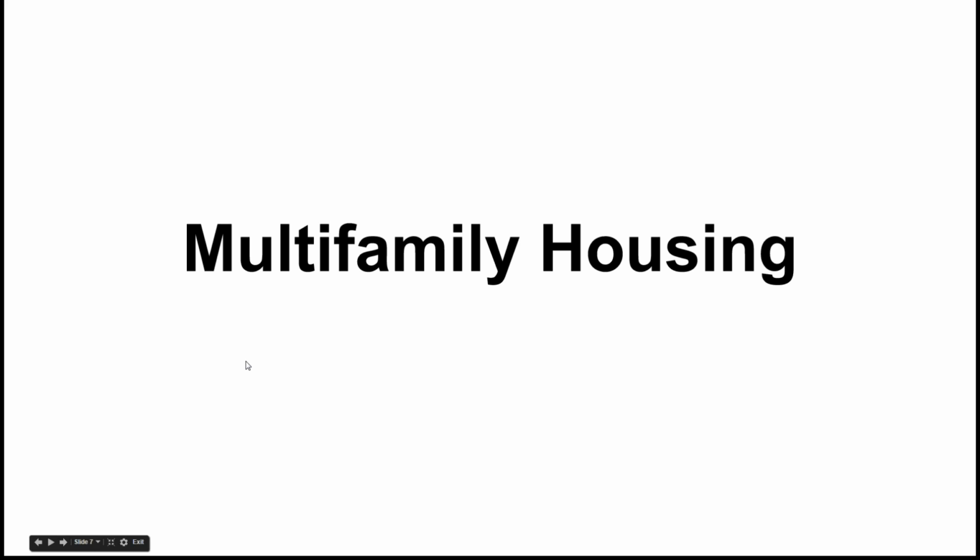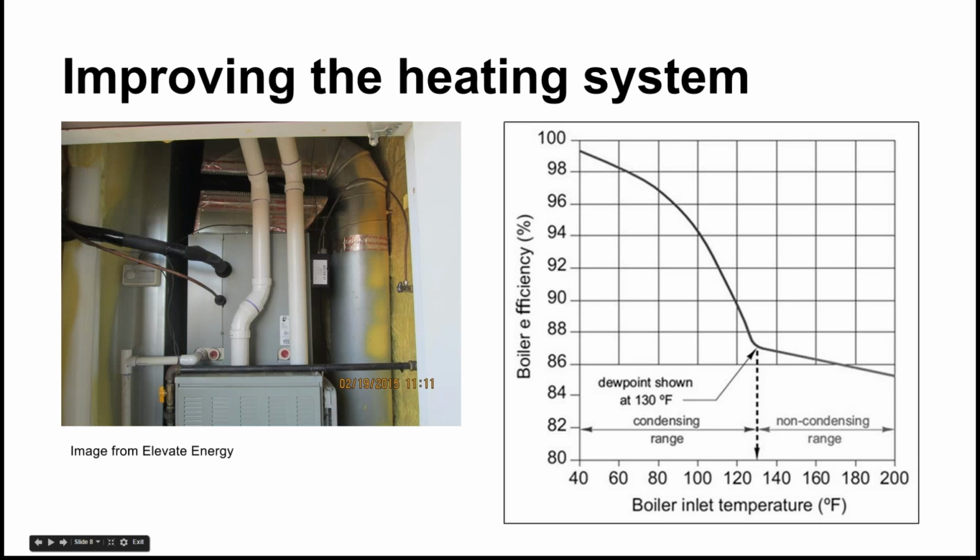So looking for every tiny place that you could air seal is maybe not the best choice here, but focusing on adding roof cavity insulation is a really good choice. It's pretty minimally disruptive to tenants. You can get it done within a day or two, depending on the size. And all you really need to do is drill a hole that you can fit a hose that puts the blown-in fiberglass into. That's all you need to do. Whereas things like wall insulation are a lot more invasive, and you pretty much need to have no tenants in there to be making that kind of improvement.